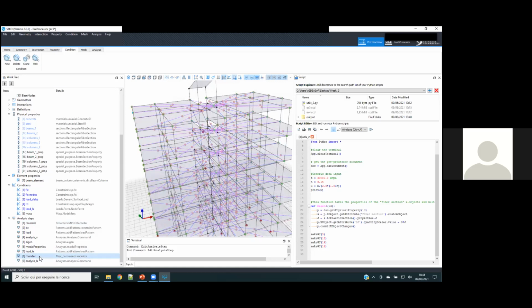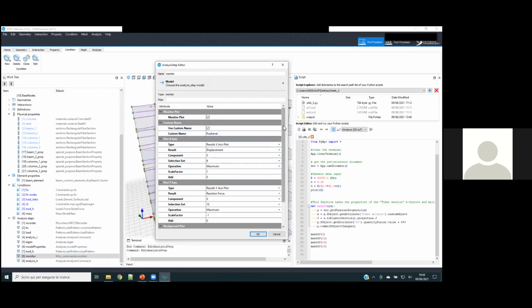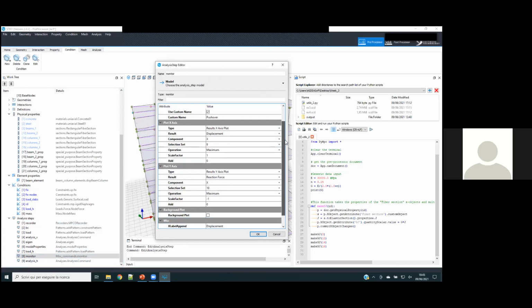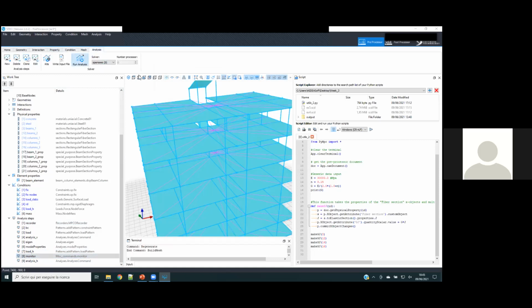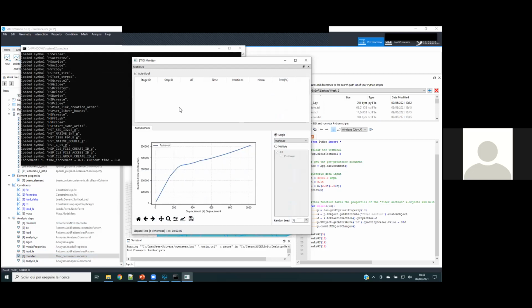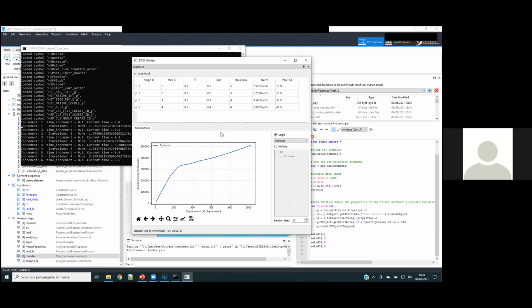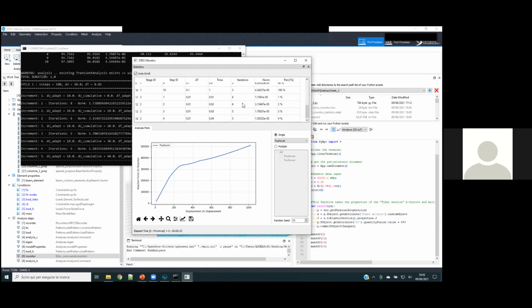And also there's something new. I also input a monitor, which is a tool that you can use to plot a graph of results in the meantime that you're running your analysis. So I'm just going to show you this really fast, how it will look when you run it. It will open OpenSees, run your first linear analysis, and then start to plot your results. It's already there because there is a subfolder. You have to remove the previous subfolder, otherwise it will just show you the previous graph. Just be sure of this.